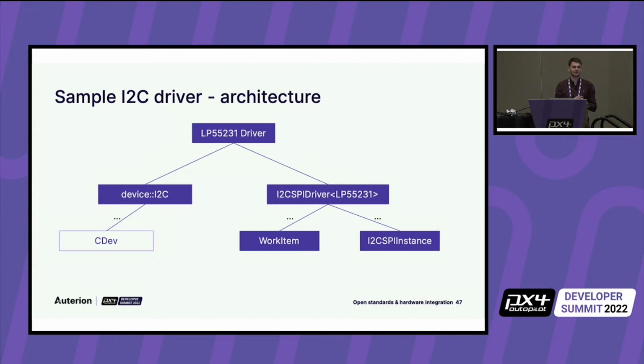It has mostly been abandoned by now because of performance. These character devices require I/O control calls over the operating system, and for performance, it's not that great. So that's why this mostly is no longer done. So when you go on NuttX and do ls /dev, you don't see all that many devices there.